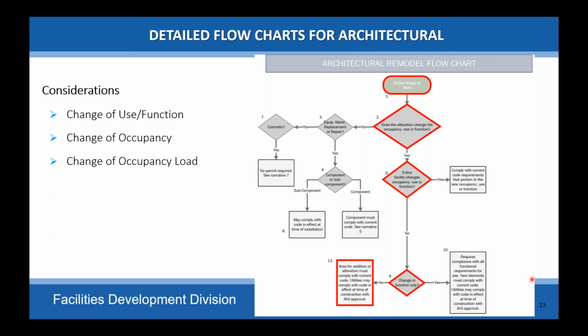So if it's not a change in function only, the area or addition of the alteration must comply with current code. The utilities, again, may comply with the code at the time it was originally constructed. A change in function will not trigger system upgrades.